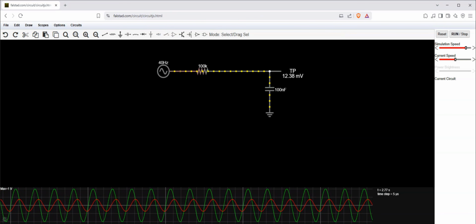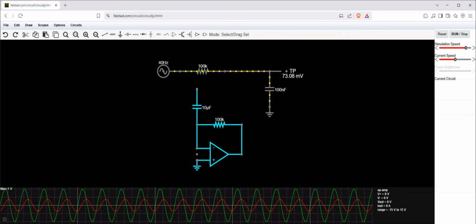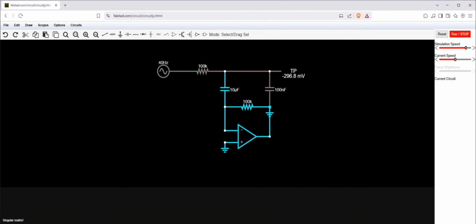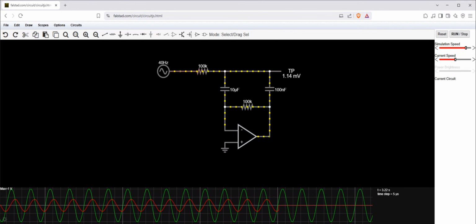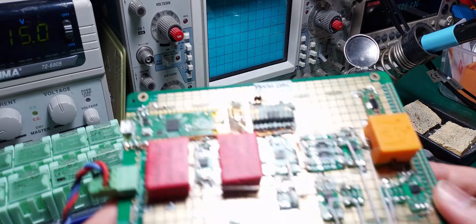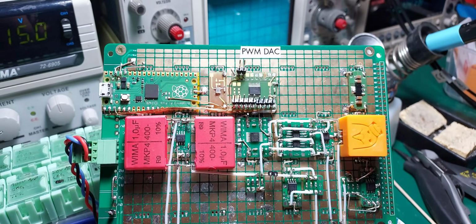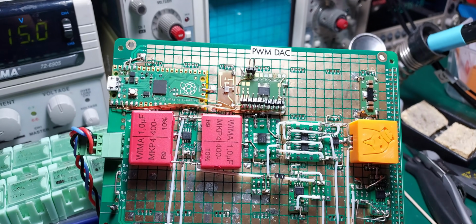As with all circuits, there are more ways than one to understand how it works. I like to think of this as a regular RC filter, but with a high-pass filtered and inverted version of the ripple subtracted from the output via the main filter capacitor. Since I didn't have the requisite 220 nanofarad TDK C0G capacitors needed to populate this board, I decided to go for a fully discrete implementation of the filter.